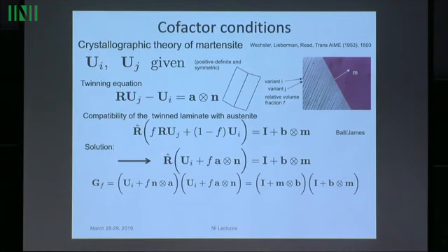That would be necessary and sufficient that this has a solution. Well, instead of calculating the polar decomposition of this, you could calculate the square of the polar decomposition, or the square of the stretch tensor, and it's just this. And of course, if the stretch tensor has middle eigenvalue 1, then this has middle eigenvalue 1. So the whole point comes down to finding a volume, and we've eliminated now the R, the R hat, that was the point.